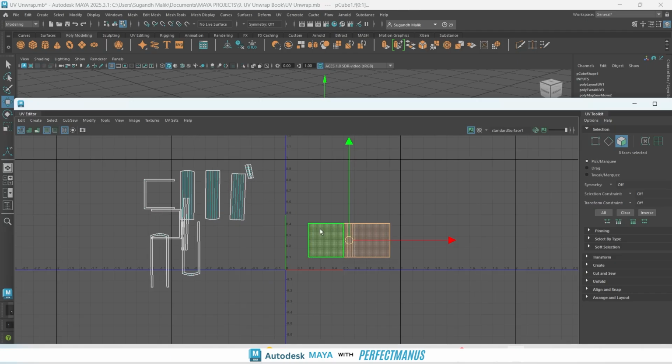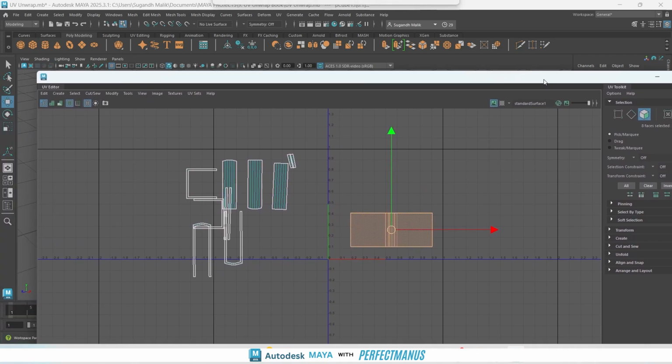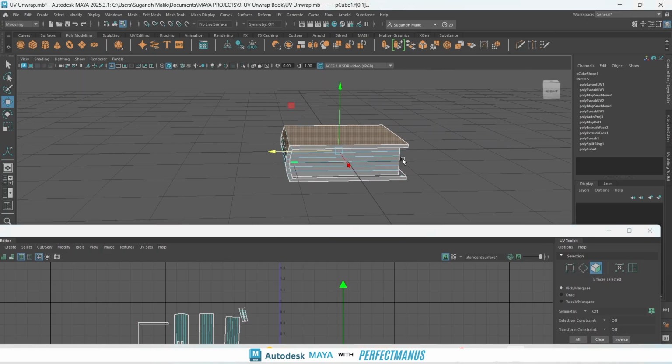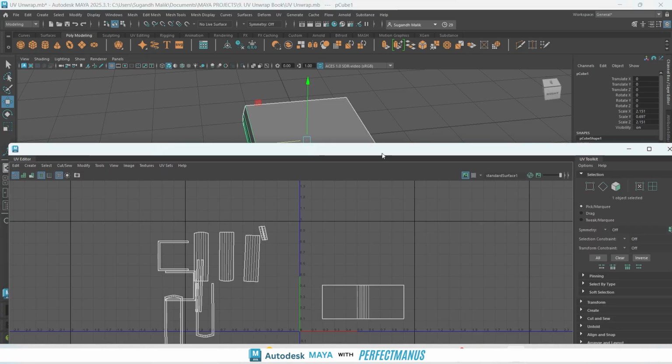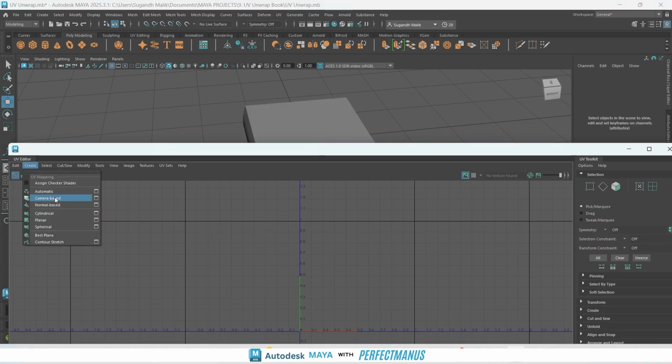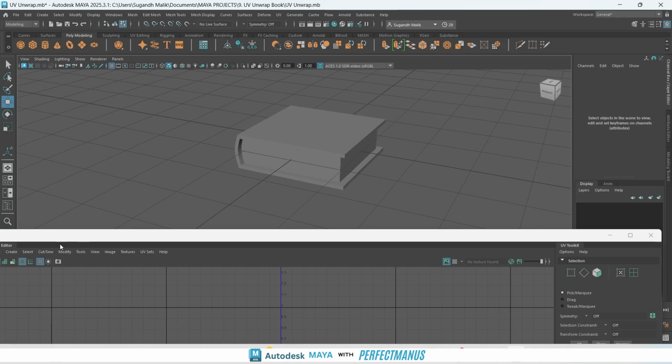Now the process will be the same, and I will show you a different way you can do it, and then I'll finish your UV unwrapping. So instead of doing it in this way, you just delete this one. You create it using camera based projection. In the camera, as I'm seeing it at this angle, just make sure that you are seeing more angles, and then select it and create your camera based UV projection.